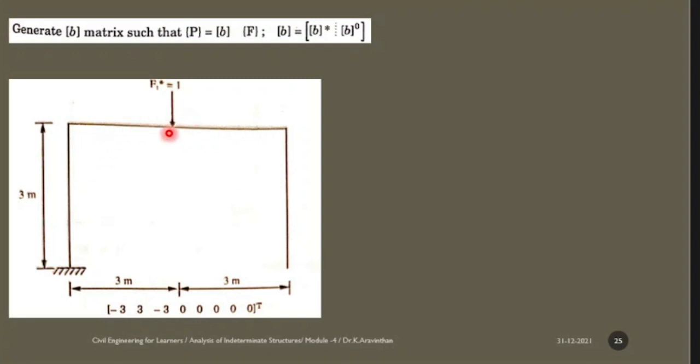Okay. Now at this joint you have taken this as an element. So now what will be your moment? You are exactly there at the load. Do you have any moment? Load will be there. What is the formula for finding moment? Load into distance. So you are only having load. Do you have any distance? 0. So 3 into 0 will be 0.